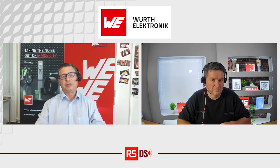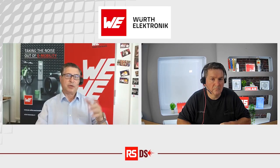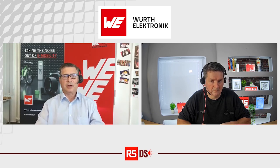I take LT-Spice, I make a small simulation, and then I calculate what kind of capacity is better for me. And I never use ideal components in simulation software. I always choose from the library. We also have a nice library for LT-Spice on our website, or sometimes it's linked directly in the datasheet, for PSpice, Altium, whatever simulator, your Cadence. You can use the simulation software with the parasitics.